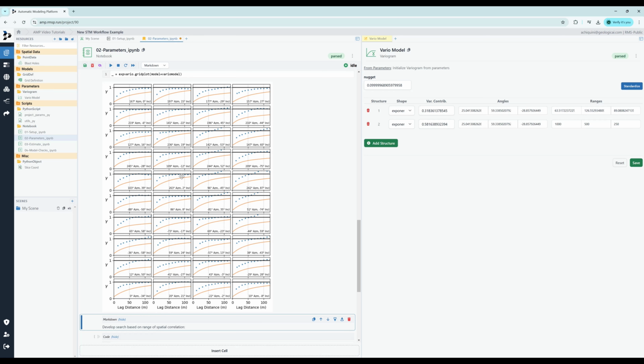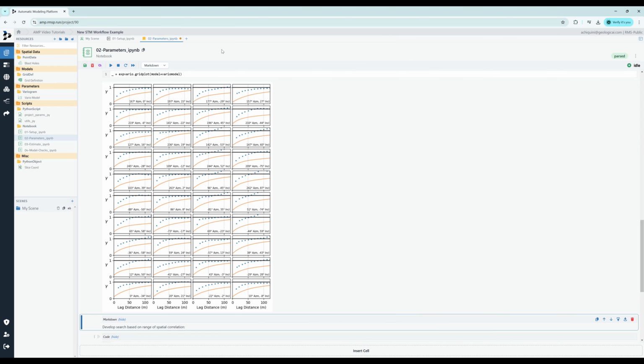Again, the checkGetResource function gives priority to resources already in AMP, or creates the resources via RMSP script if they don't exist yet. This allows you to edit a variogram model or a search and so on dynamically in AMP and carry those changes forward in your workflow, instead of always overwriting and utilizing those initial parameters defined in the RMSP script. Let's close this here, and now let's delete this variogram model because the change we've made is not correct against our data.